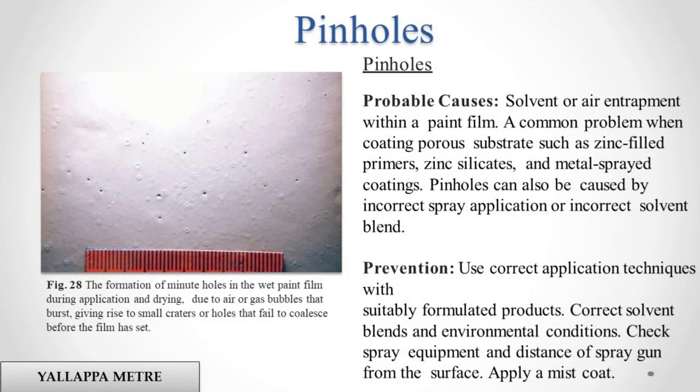Pinholes. Probable causes. Solvent or air entrapment within a paint film. A common problem when coating porous substrates such as zinc-filled primers, zinc silicates, and metal-sprayed coatings. Pinholes can also be caused by incorrect spray application or incorrect solvent blend. Prevention. Use correct application techniques with suitably formulated products. Correct solvent blends and environmental conditions.